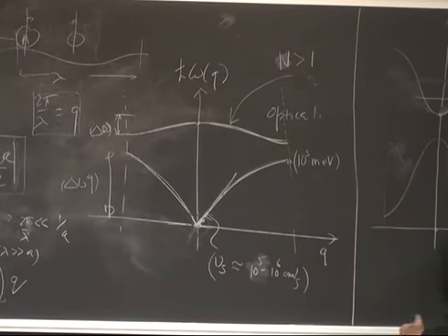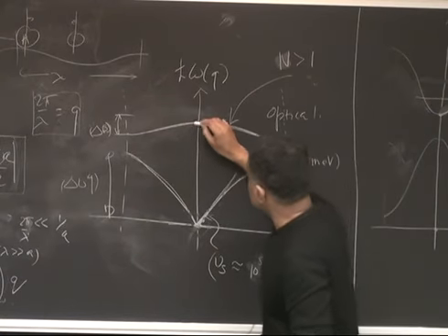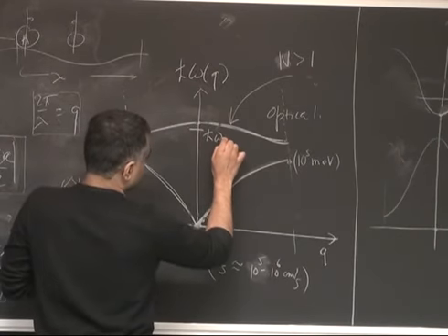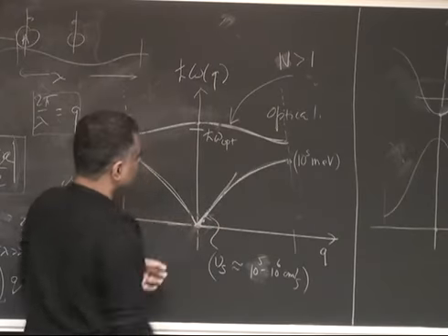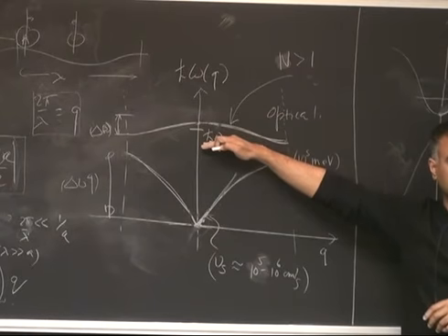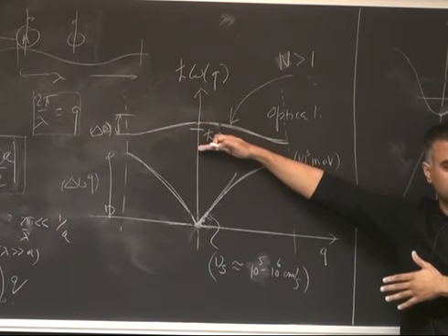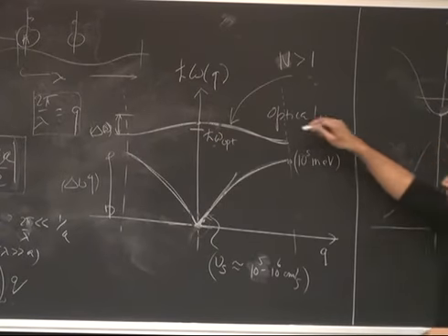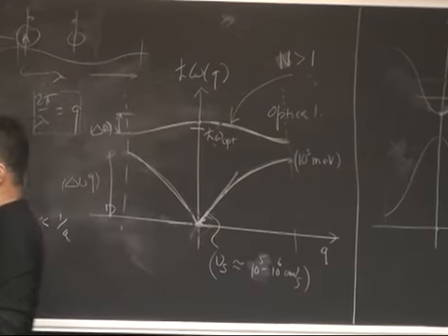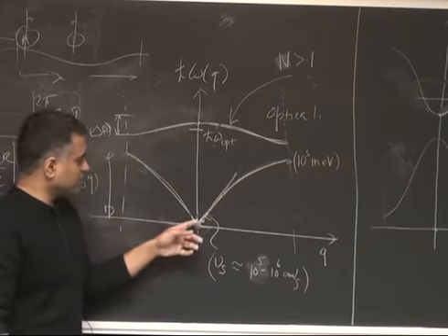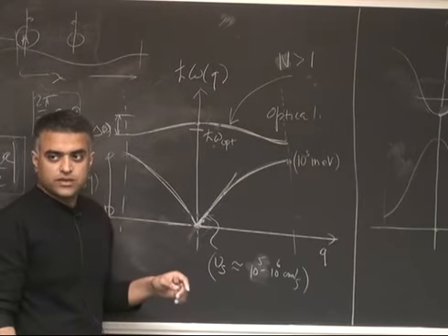So for example, you can see right away that unless the electron energy is larger than the optical phonon energy, let's assume this is very flat, let's call it h bar omega optical. If the electron energy is not larger than the optical phonon energy, it cannot emit an optical phonon. It cannot excite it, right? Because you need a certain threshold to emit the optical phonon, right? But when it does, the rate of optical phonon emission in compound semiconductors is way higher than the rate for emission into acoustic modes. Does it make sense?